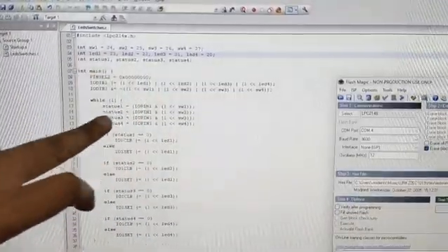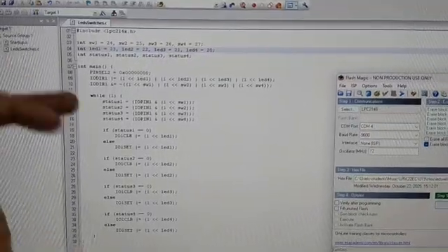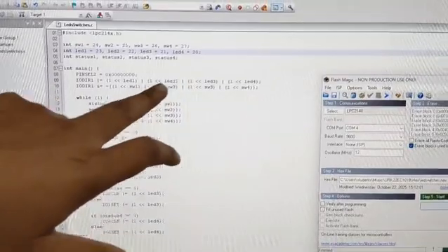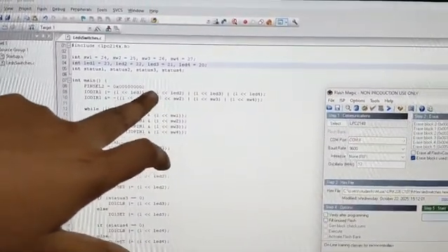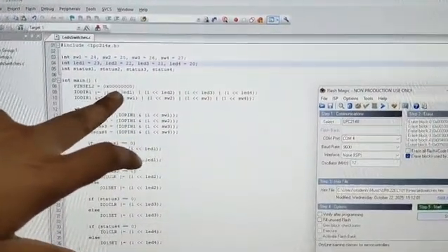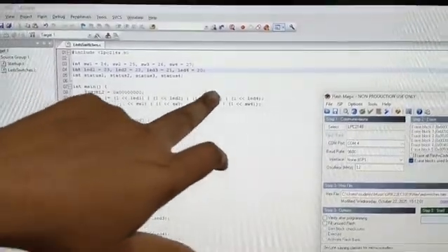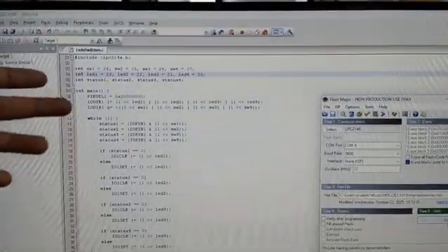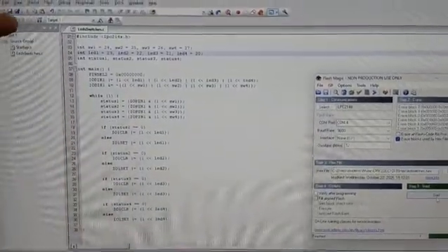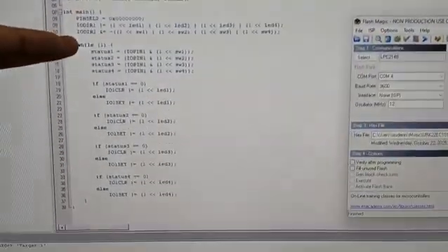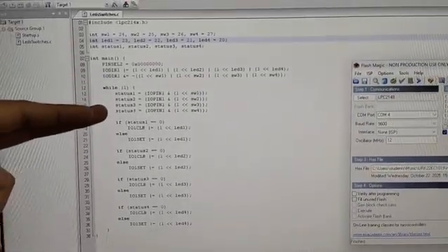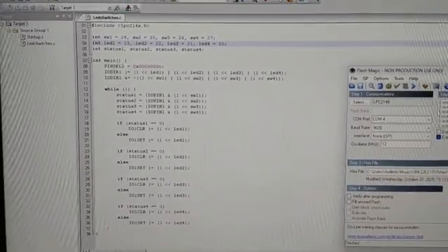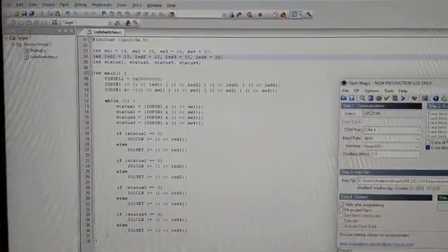and 4 status variables. Similar to the previous code, only in the IO direction we are adding another line of code. We are using the OR operator to set the direction for each of the LEDs and each of the switches. And the remaining we have just duplicated from the previous LED switch code. Previously we used 1 status. Here we are using 4 statuses and 4 conditions. So this is 4 LEDs and 4 dip switch integration.